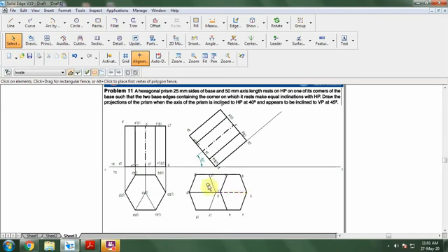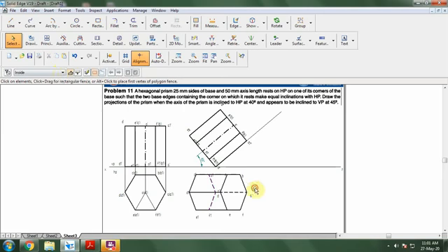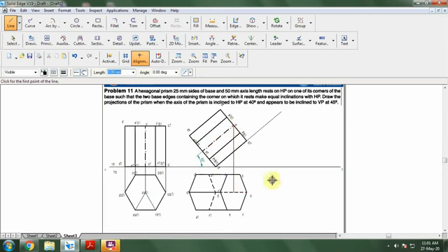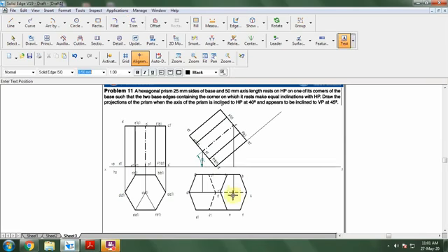For that, the lines connected are this and this. So that also will be invisible. Make that a dotted line and 0.5 mm. The last dot is the axis. So I want to take O and project O onto this. Similarly, O onto this. When you join the axis point, the axis point will not be visible because it is behind the visible and invisible edges. This will be O and this will be O1. So this is about the second position.